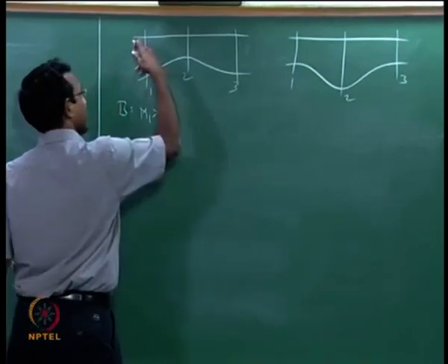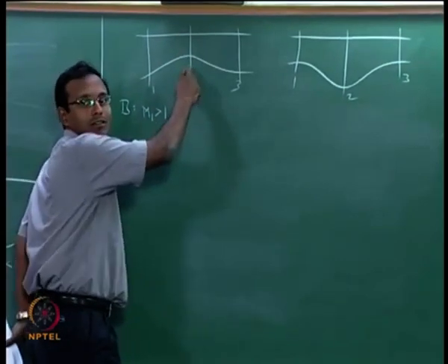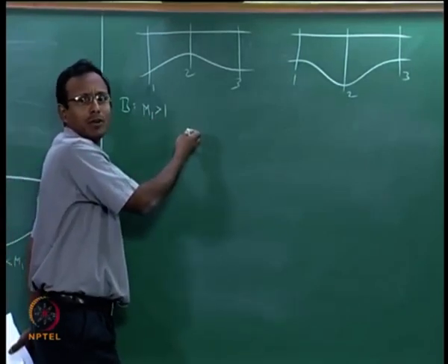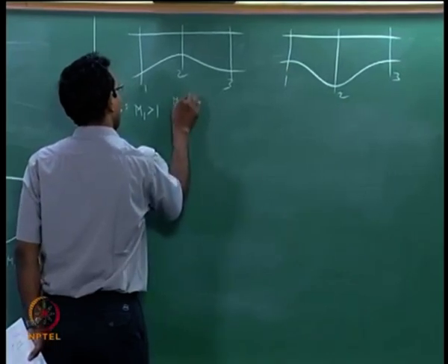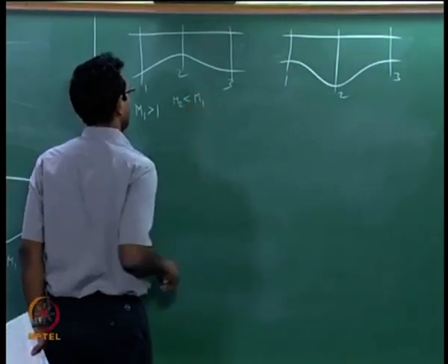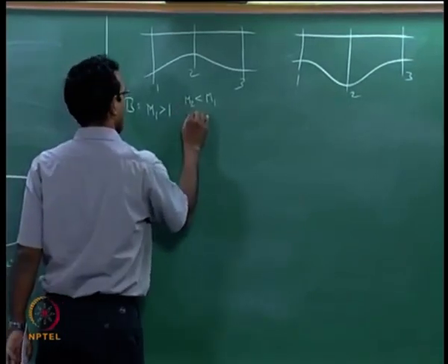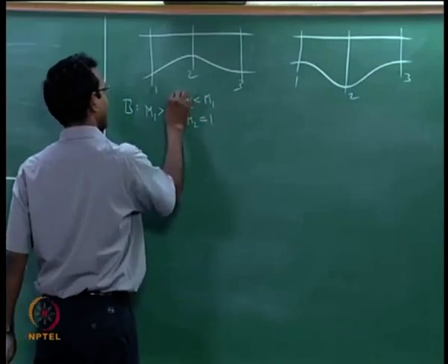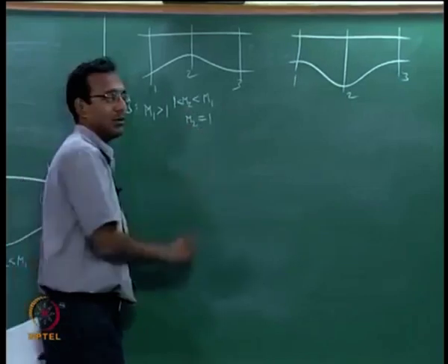It's supersonic, it is going to go towards M equal to 1, which means 1.5 will go towards 1, maybe it will become 1.1, I do not know. All I can tell is M2 less than M1. Let us consider a case where M2 is something like 1.1, and in another case it is exactly equal to 1.